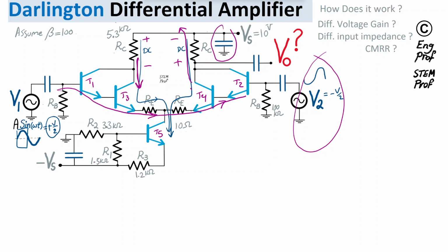And because of this cap, which is a bypass cap, AC-wise this is shorted, so this node AC-wise is virtual ground. Therefore the output voltage, which is a single-ended output voltage, is basically just this plus-minus between the output and AC ground, or virtual ground AC. So this voltage drop with this polarity, which matches exactly the desired polarity for Vout, is what we are expecting.